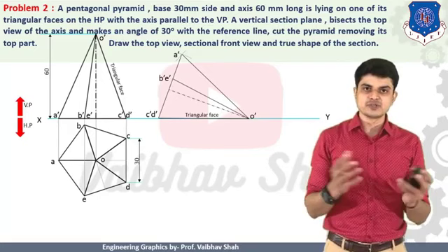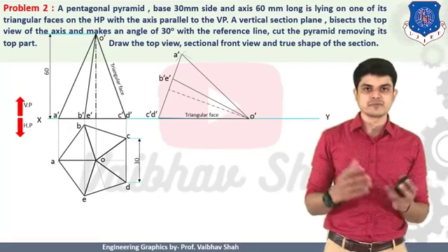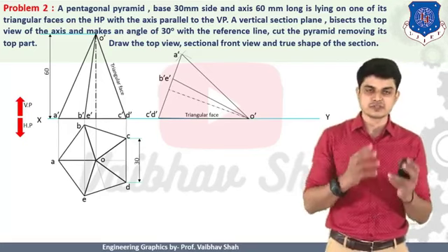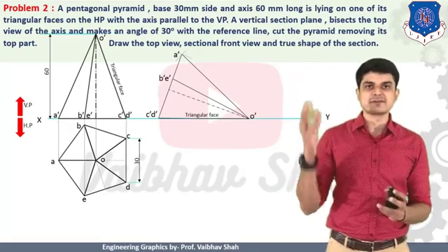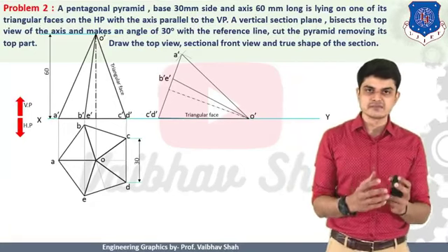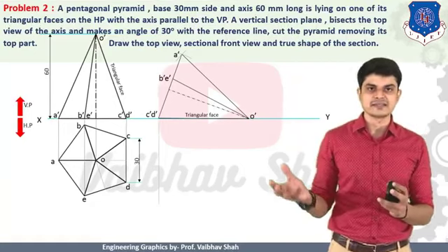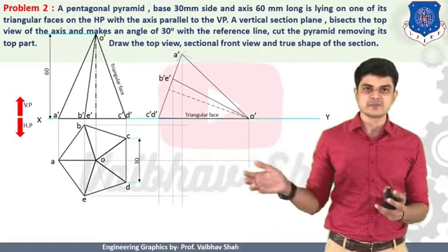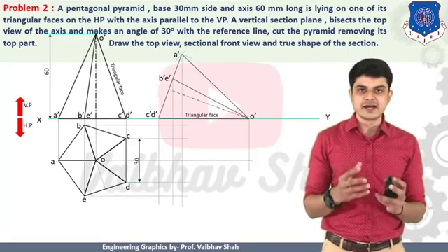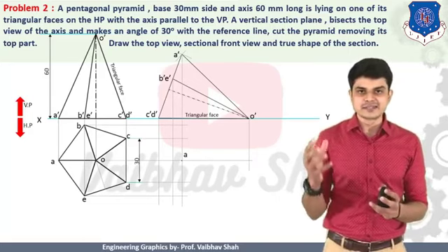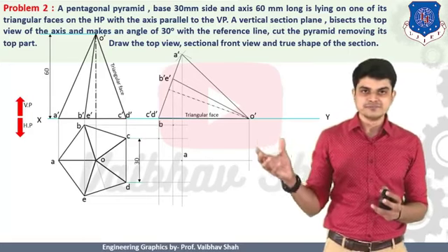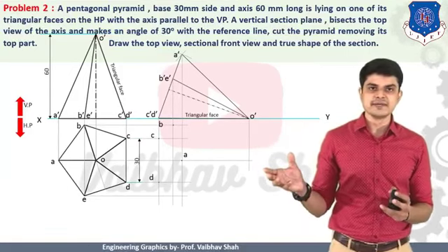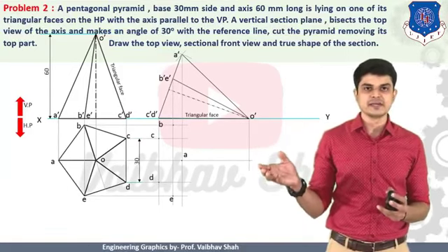After getting this object, we should finally draw its top view from the top direction. So let us observe this object from the top direction. When we observe the object from the top direction, we can have vertical lines of projection like this from each of the points, as you can see, and the horizontal lines from the previous points. And then we should define the points of intersection like A, B, C, D, E. And then finally we will be defining your apex point somewhere here.